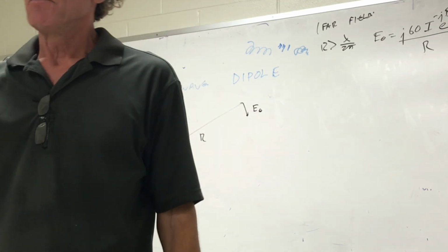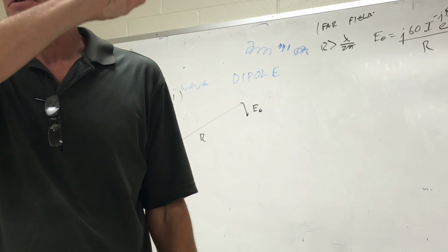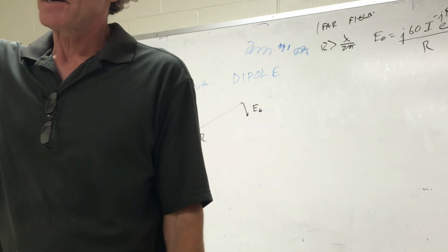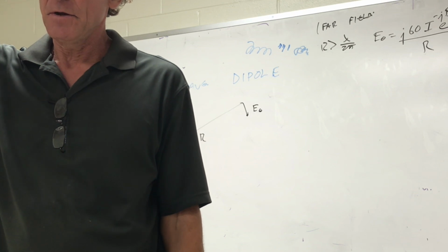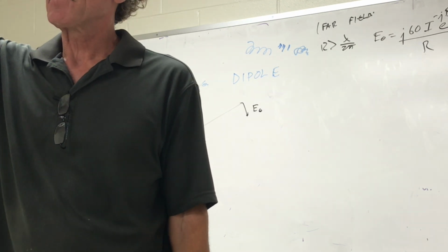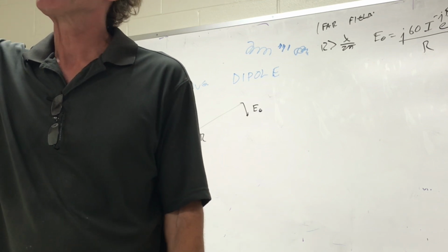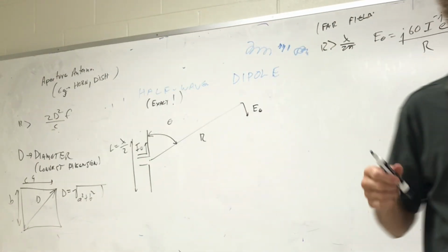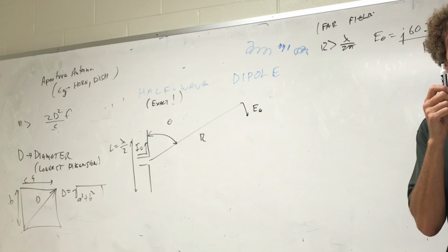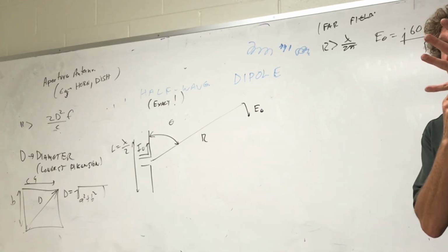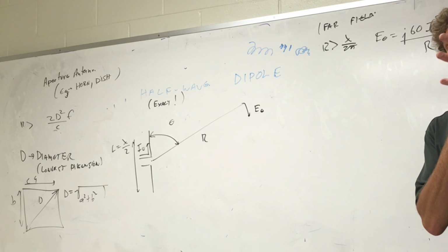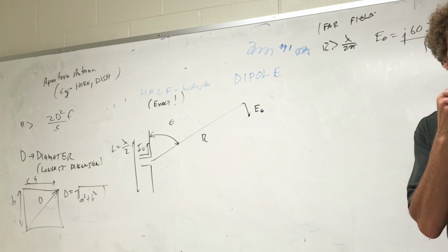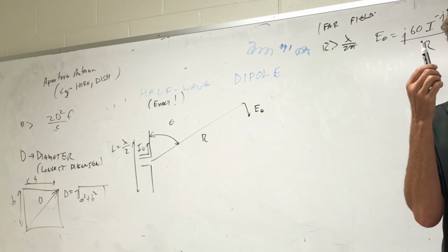The reason that's important is when you're doing antenna measurements, you know where the anechoic chamber is on the fourth floor? Do you know what the anechoic chamber is? If you don't, remind me afterwards, please, and I'll take you up there and show you. It's a bunch of pyramidal horns that absorb electromagnetic energy. It's about the size from this wall to that wall. The field radiated from the antennas in there has to be in the far field to get any meaningful reflection and transmission coefficients. But if you go at too high a frequency for an aperture, then this is near field, and all your measurements go to pot. This is the thing you have to be aware of.